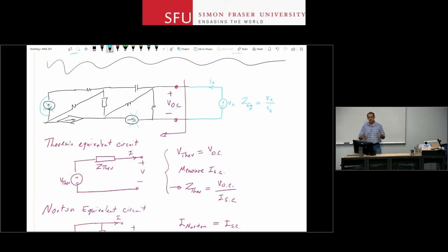to figure out what is the input impedance of a circuit or what is the output impedance of a circuit. And we replace a very complex network potentially with just one resistor as, let's say, the output resistance or input resistance of the next stage. So this is a technique that we are going to use very often. And this is how we do it. You attach a test source to that port, let's say voltage source, you measure the current that goes into the circuit, and from that point onwards, Vx over Ix is your equivalent impedance.